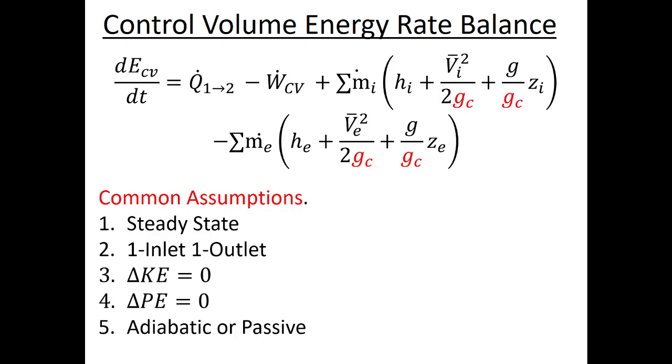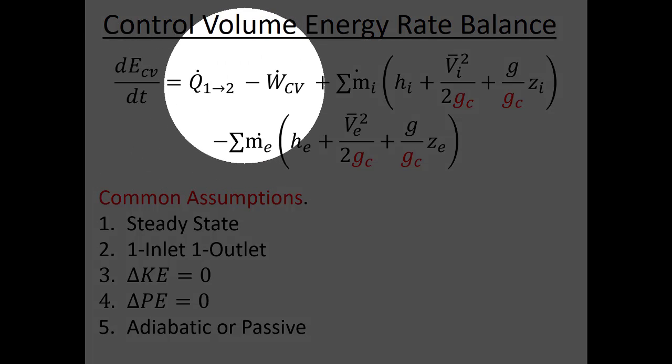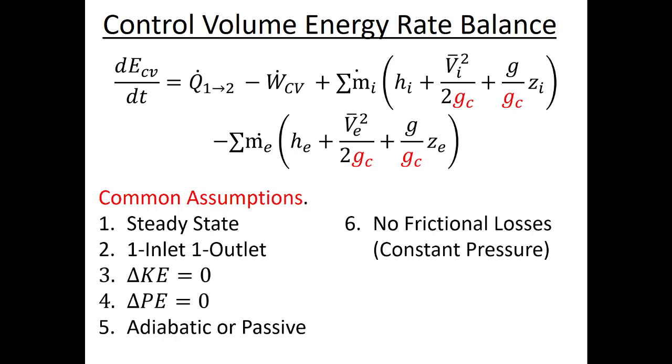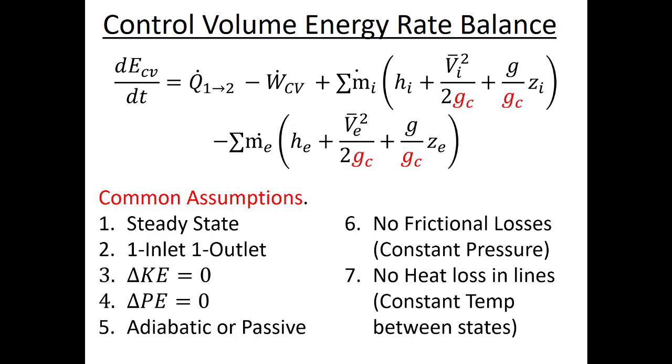Right? We'll often assume that open system processes are simple processes where it's either the heat transfer rate or the power that matters, but not both. So usually we'll cancel one of those two things out. If we have processes that are chained together, we will typically assume that there are no friction or heat losses in whatever lines we're using to connect our different components.